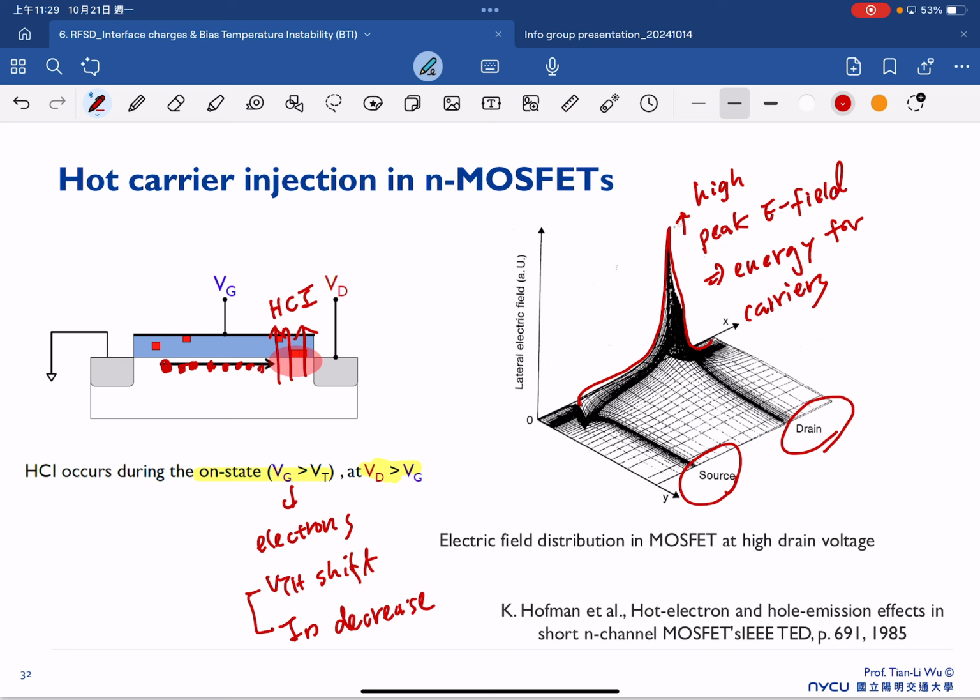But if you look at hot carrier injection, you put it in Google Scholar, you look at the last 5-year literature, you find out that these effects get even more crazy nowadays in our advanced technology, because in our advanced technology, we have a shorter channel, we have a shorter distance. In other words, that means we have a higher electric field. The high electric field always gives a high energy to the carriers inside the transistor. So that causes the serious problem of hot carrier injection.